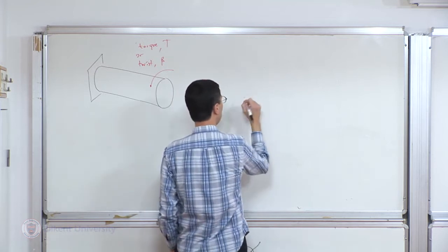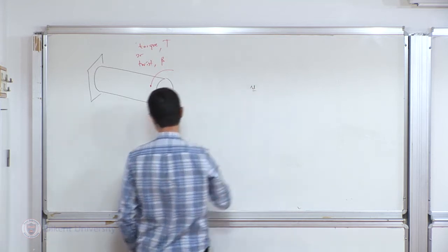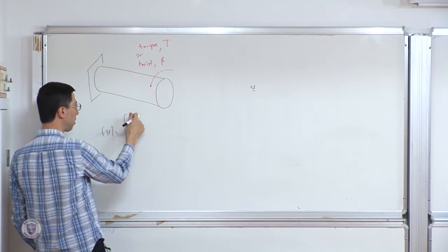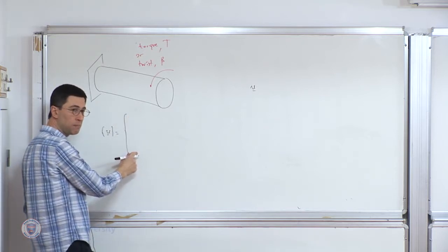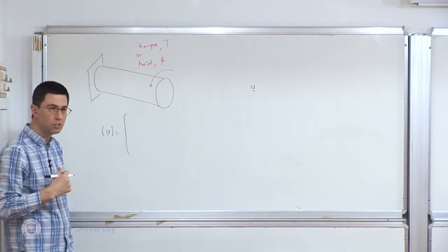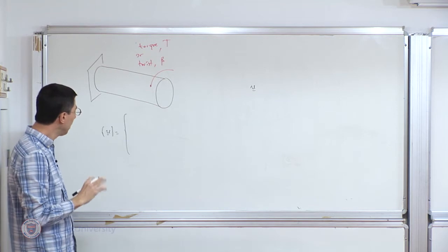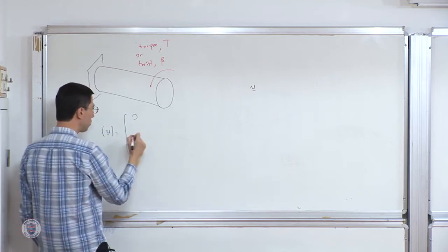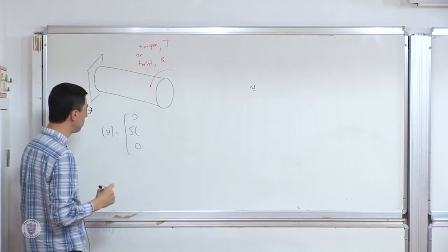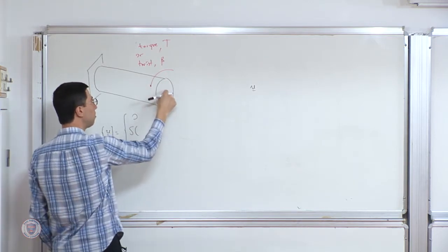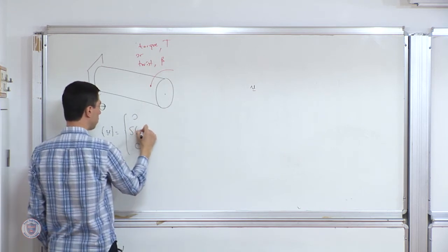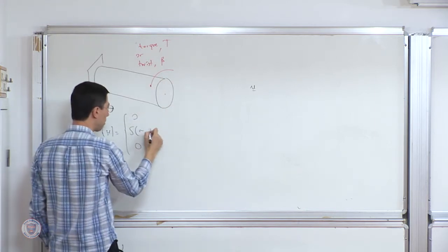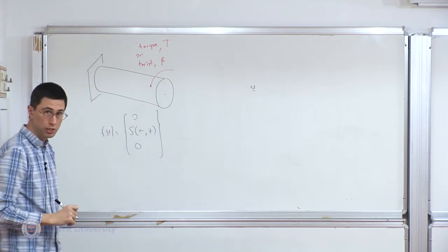The solution proceeds pretty much in the same way. And essentially what we did was we started with a proposal for the displacement. Now that proposal for the displacement took the following form. We argued that we do not expect in a cylindrical coordinate system any radial or axial displacement. These are intrinsically motivated by our understanding of the problem from our first mechanics course, right? Which assumes isotropy. So if it's not isotropic, other things might happen. But presently, it's zero. And what we expect is a tangential displacement. And then we argued that that tangential displacement will increase with the distance away from the axis of the cylinder. So it depends on r. And also, this end is fixed. As I move towards that end, it will move more and more, so there will be some dependence on the axial position as well.